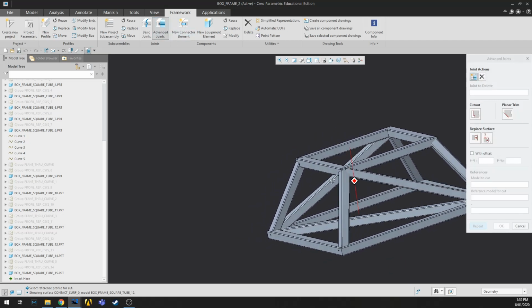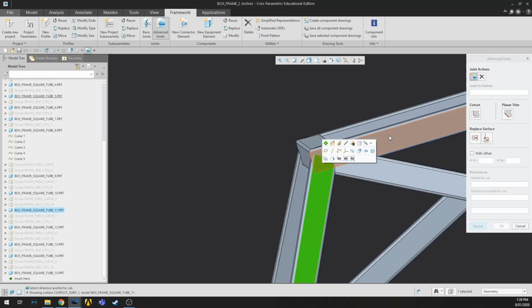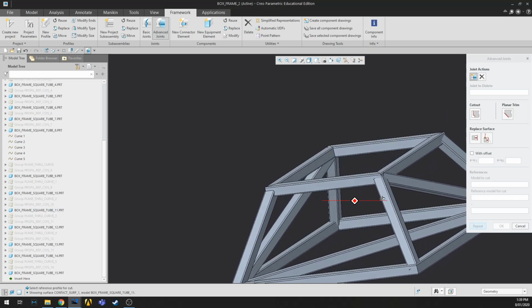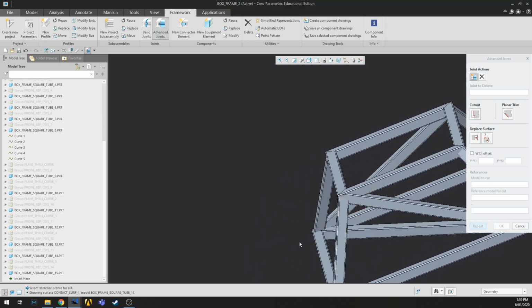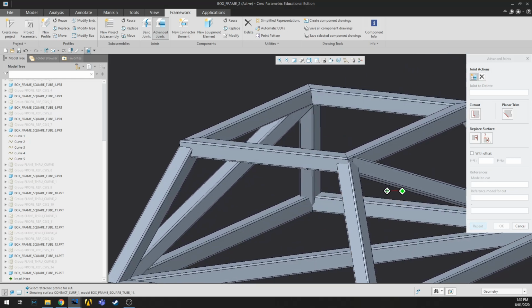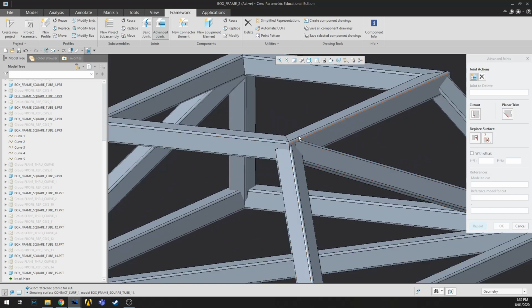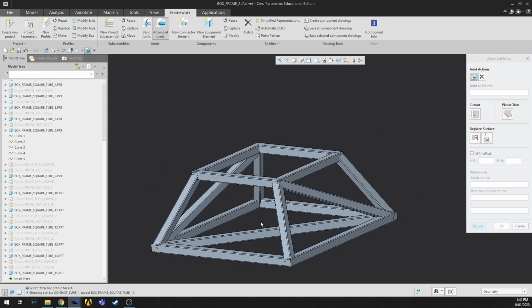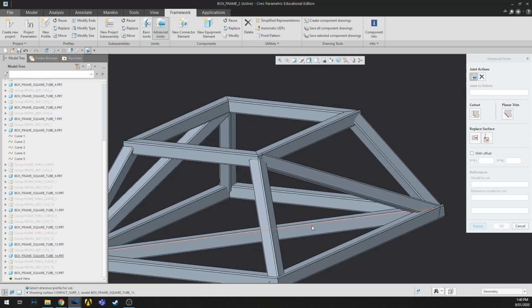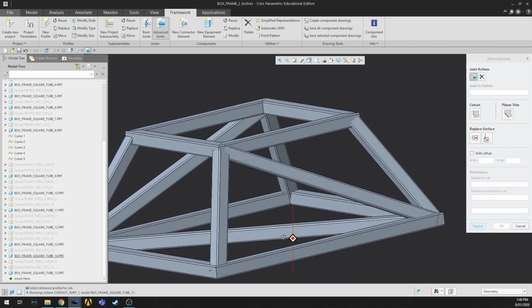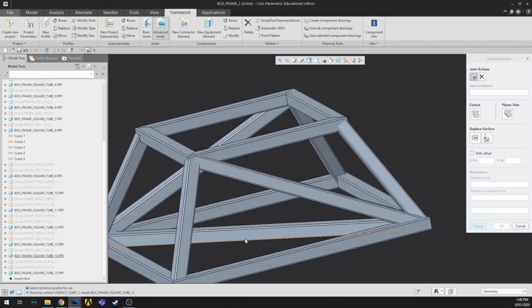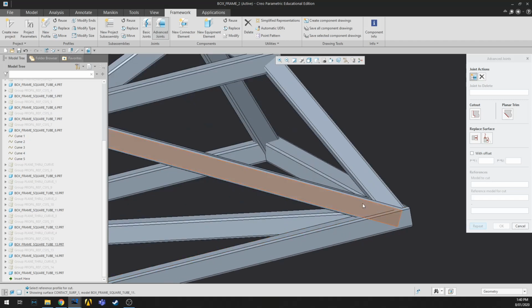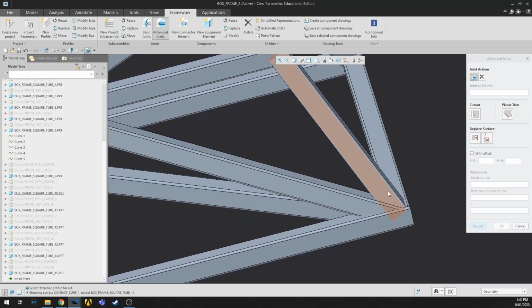So anyway, we're just going to go around and finish notching this up. This example maybe doesn't demonstrate it super clearly, but one important fact when you're making your notches is you want to notch things in the way that they're going to be built. Otherwise, when you go to assemble your shapes, you might not be able to actually assemble it. So I don't think there are any great examples here. Just something to be careful. You would need to notch this to suit that, and this as well to suit that one.